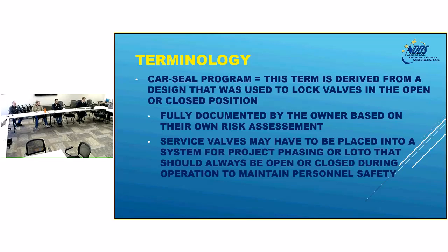What happens if the pressure is too high? What happens if the pressure is too low? What happens if we get a break? What happens if this valve is shut inadvertently and this one's open? And it will cause these different conditions to occur. And they do a complete fishbone analysis, and usually what shakes out of that is they'll find 2 or 3 valves that just absolutely have to be in specific positions, or something very bad could happen. And so they develop a car seal program to ensure that the operators are leaving those valves in the right positions.